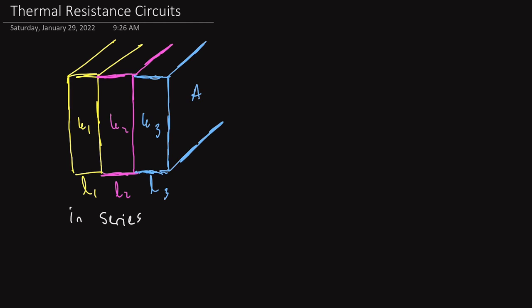And so to get started, we're going to look at thermal resistance. Specifically, we're going to be looking at how heat flows through a system via conduction. If we recall something from electrical physics, V equals IR was Ohm's law. It tells us that the potential difference is equal to the current times the resistance in a particular circuit. Just like with electrical circuits, we can look at thermal circuits in a very similar way. If we think of voltage, this potential difference, as a difference in temperatures between two places or two mediums, we can do that.